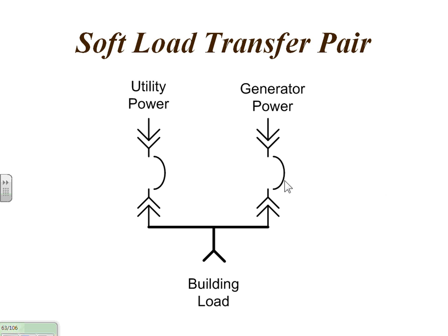We aren't going to give a close signal to that breaker until the synchronizer part of the paralleling gear has the voltage amplitude matched. We're at 480 here; we want to be 480 here. And we want to have the frequency matched. We can't have any phase shift between the two.